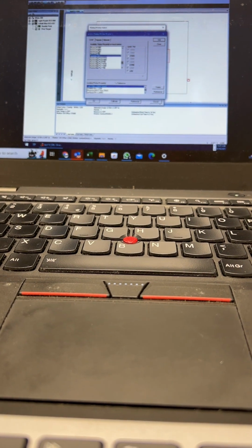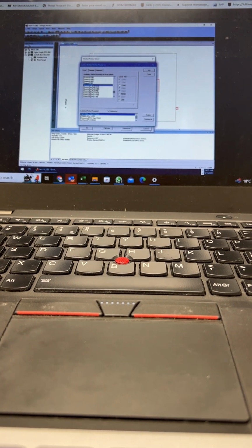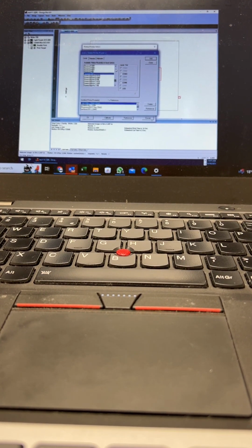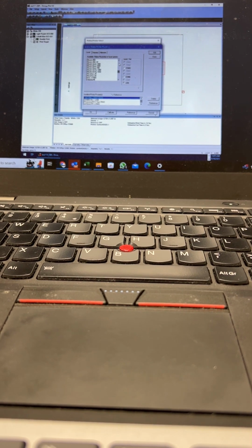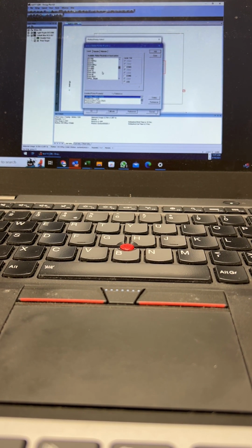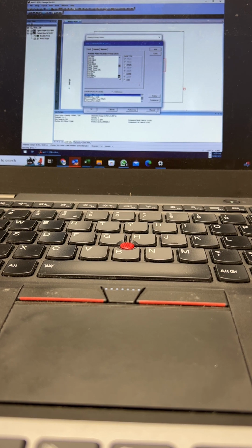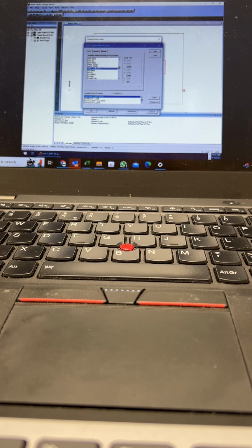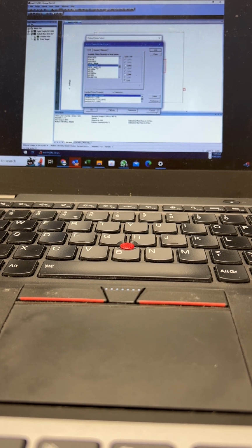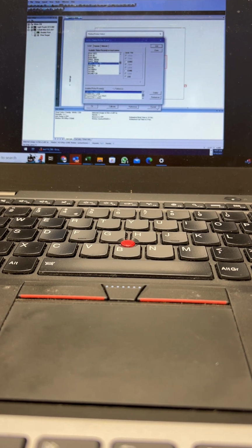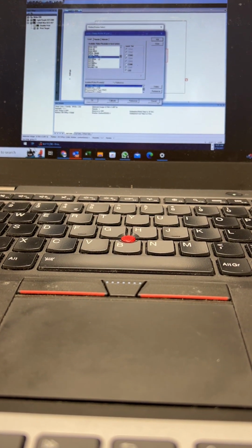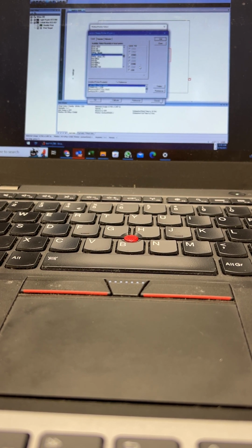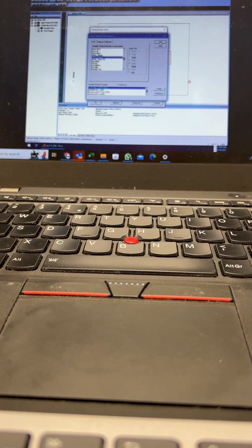If the plotter is not listed, so for example, the Suma S3s are not in the software at this point, or the Suma S2s for that matter, you can go in and install what's called an HPGL plotter. So we do have a bunch of different HPGL plotters. These are just basic drivers for each of the plotters. So usually it's going to be HPGL Simple or Smart. It may be the PD, page display. But generally go with the Smart or Simple, installed on a port, and then see what that does from there.